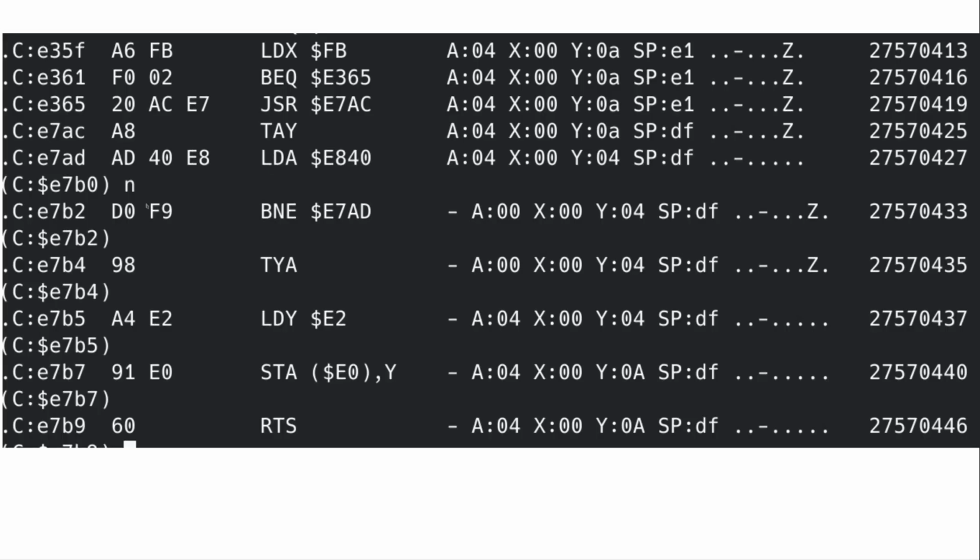And in the code itself, when you write something to screen, we load the value from that port bit, from that port, and if it's set, which means the video is on, which means it's in the 200 raster lines that actually show something, it loops back to itself. And only when it finds out, okay, I'm outside of that active video area, data is being written to the screen.